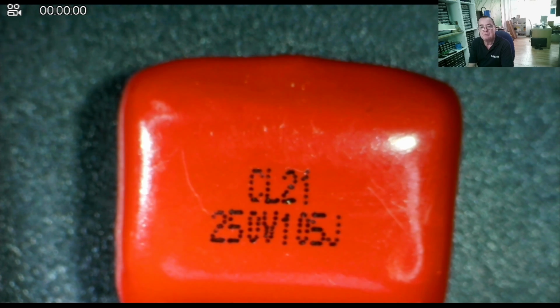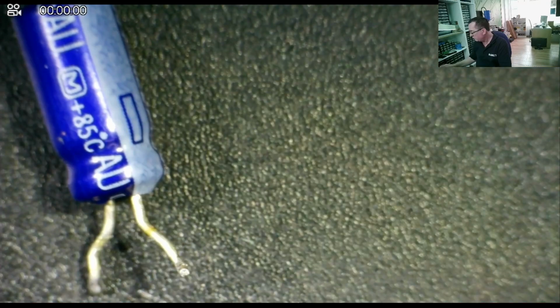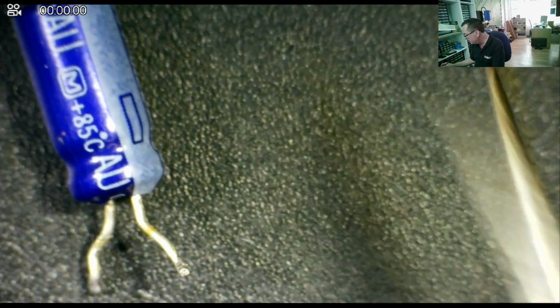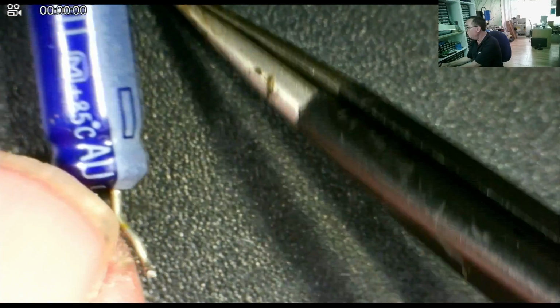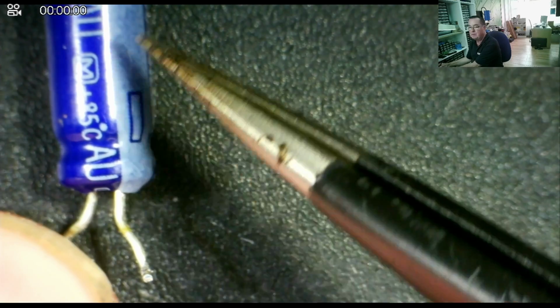So we see the same sort of patterns over and over again. This is around the sort of value of capacitor where we go more into the electrolytics. We can get them smaller than 1 microfarad. So let's have a look at a few electrolytics and how they are marked. There's a few different things to know with the electrolytic capacitors. I did mention polarity. You can see this is marked with the white stripe, the negative on.